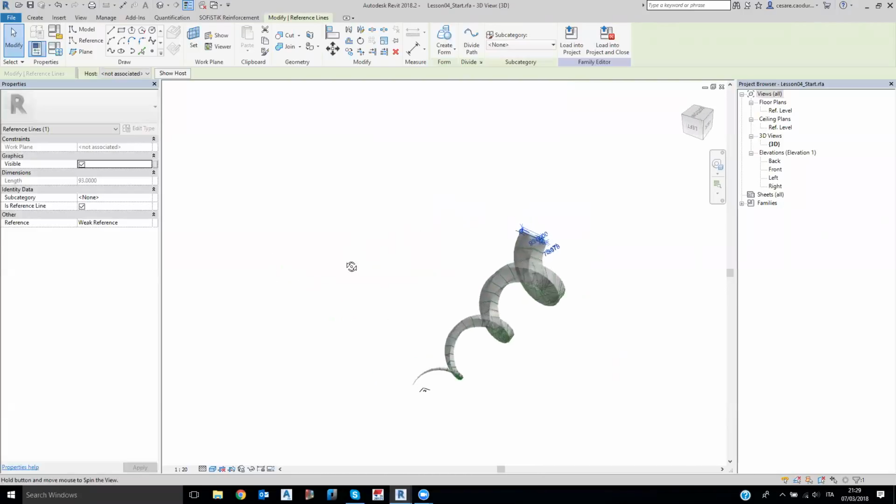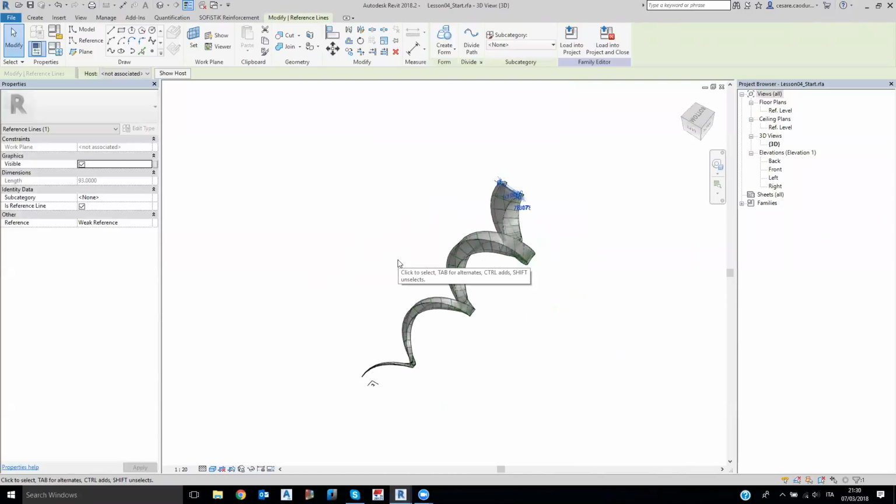So this is more or less the way I'm using to create curtain walls, substructures, complex substructures for shelters. You just need to draw the exact shapes that you want to replicate. You can do really steel structures, concrete structures in this way, very complex shapes, just always using the same way. Building a section, building a grid of connected curves, and then using coordinate systems to place the sections in the correct way against the path, and then using the solid loft by cross sections to create the real solid inside Revit.